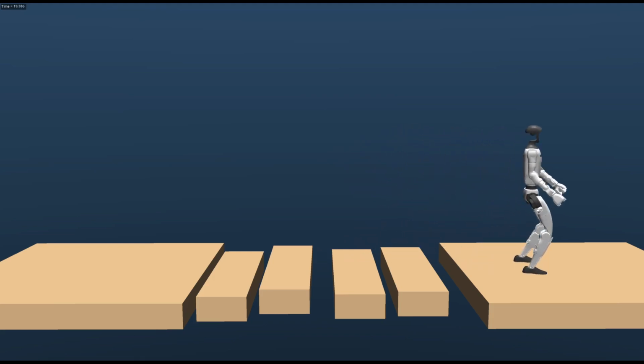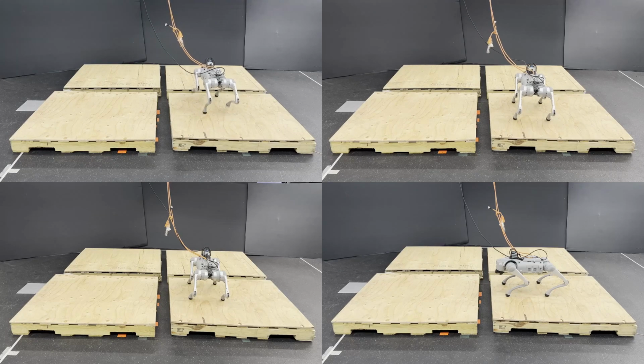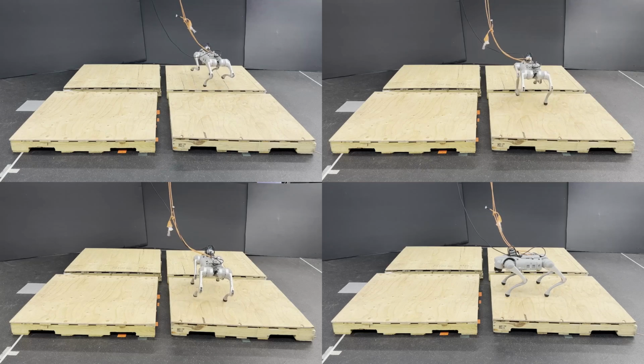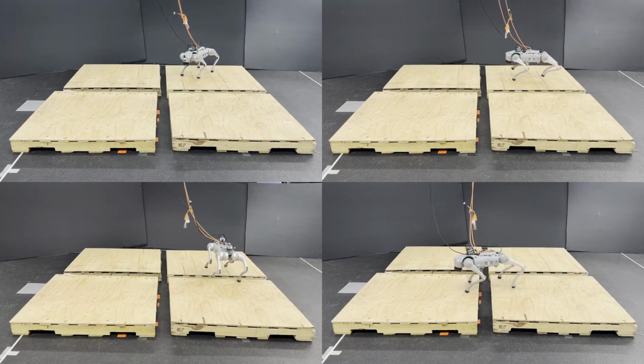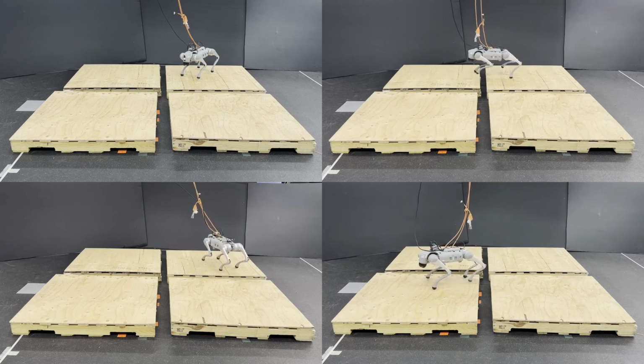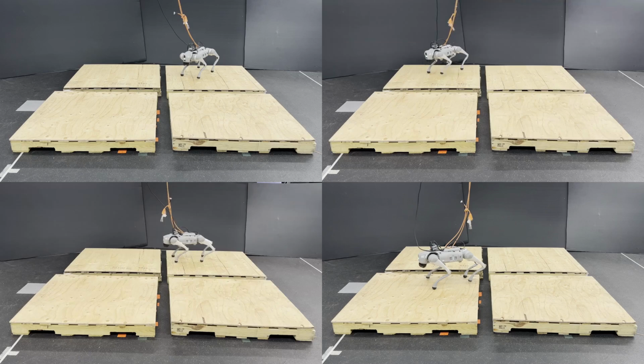To choose terrain samples, a random number is sampled between 0 and 1. Each piece of terrain within the kinematic limits of the robot is associated with an interval between 0 and 1 and weighted by its area within the kinematic limits. To prevent resampling the same terrain combinations, a tree structure is used to keep track of the available combinations.